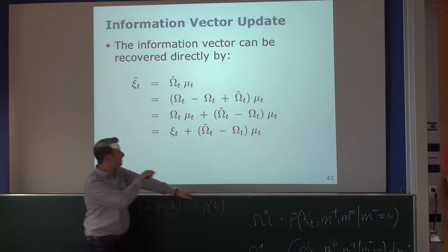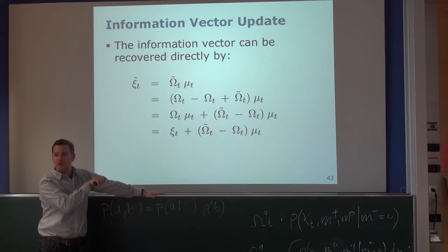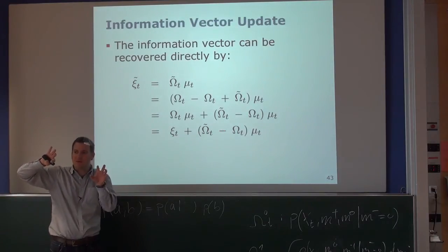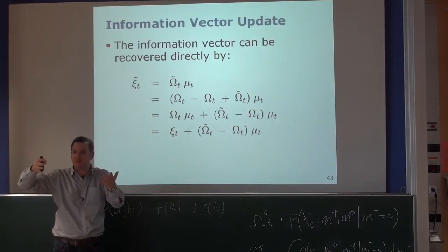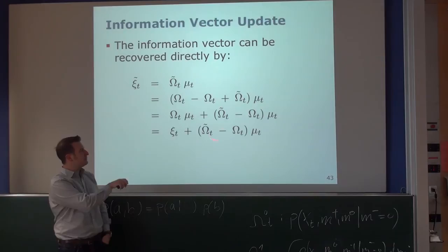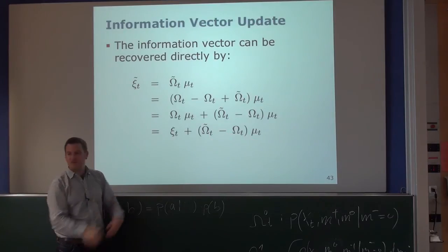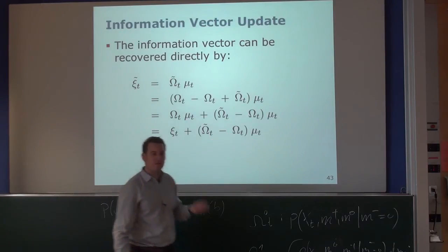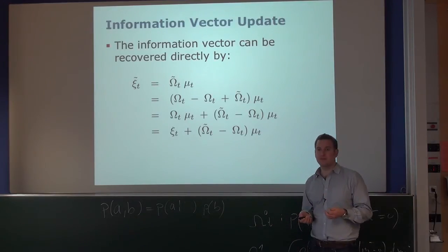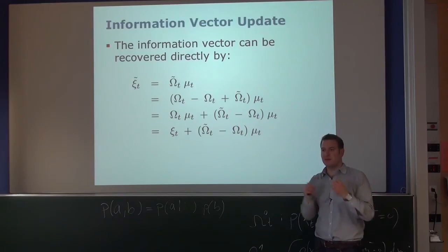So this guy here will be basically 0 everywhere, except for the few landmarks which changed due to the sparsification, where the sparsification led to a change in the values of the information matrix. So there are just a small number of elements which are non-zero. And so I can just update my information vector very efficiently without having to compute these matrix operations in reality. That's kind of the key trick again.